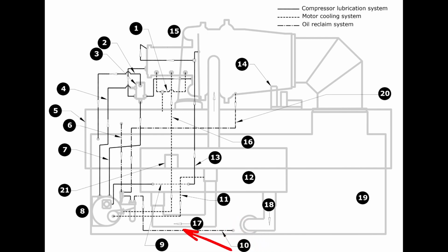we're going to go through this valve and then up, and we're going to get drawn into our filter assembly and then through that and into our eductor block. And the same science is happening here. We're taking hot gas, high pressure refrigerant, and injecting it into this port. This nozzle assembly in here is going to create a Venturi siphoning effect. That Venturi effect is going to cause a draw on these others while also flashing off any liquid refrigerant, and then we get our oil directly back into our tank.